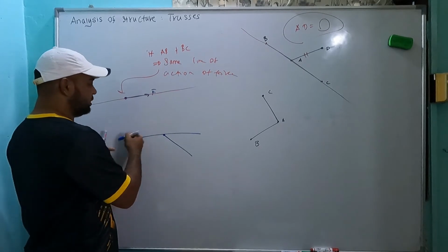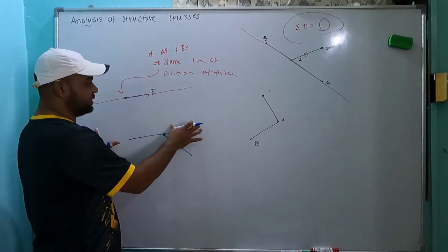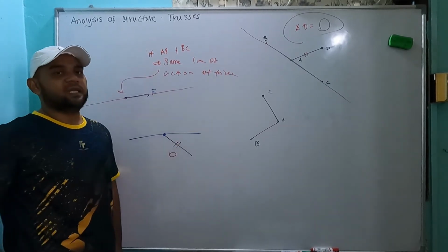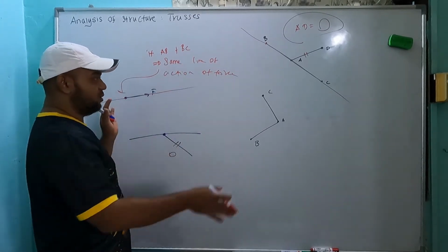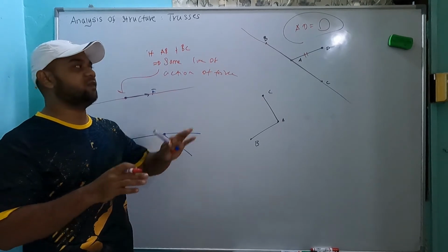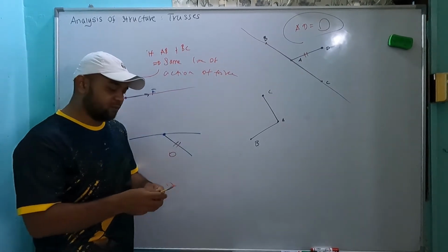Okay, these two are on the same line of action, first part and second part are the same line. So the third part here must be 0. Okay, the orientation doesn't matter, as long as two of them are on the same line of action of force, the third one must be 0. So to demonstrate this one, let's say we have this.